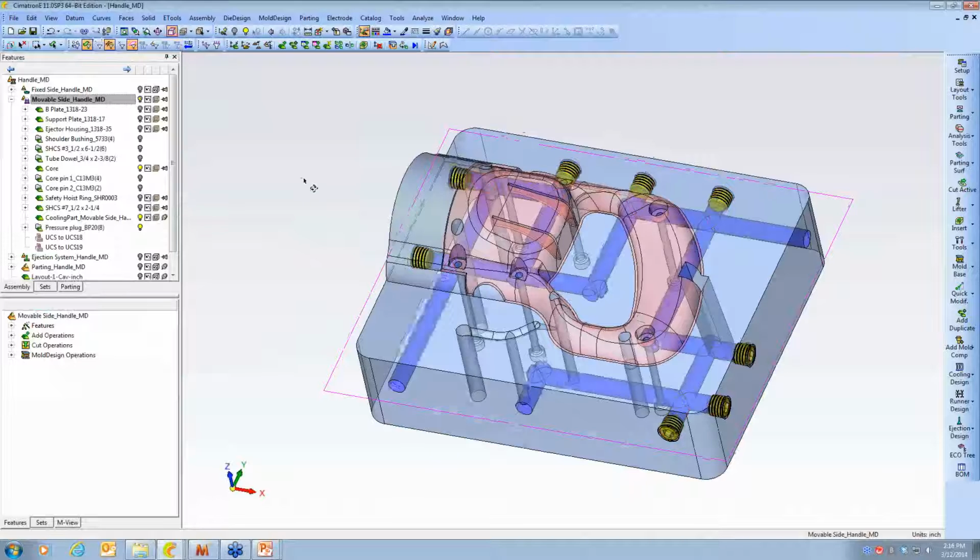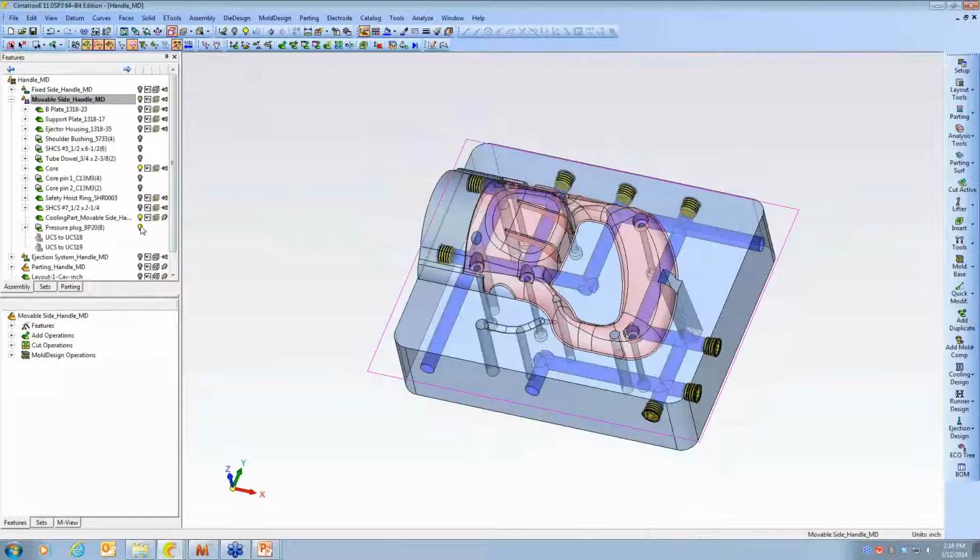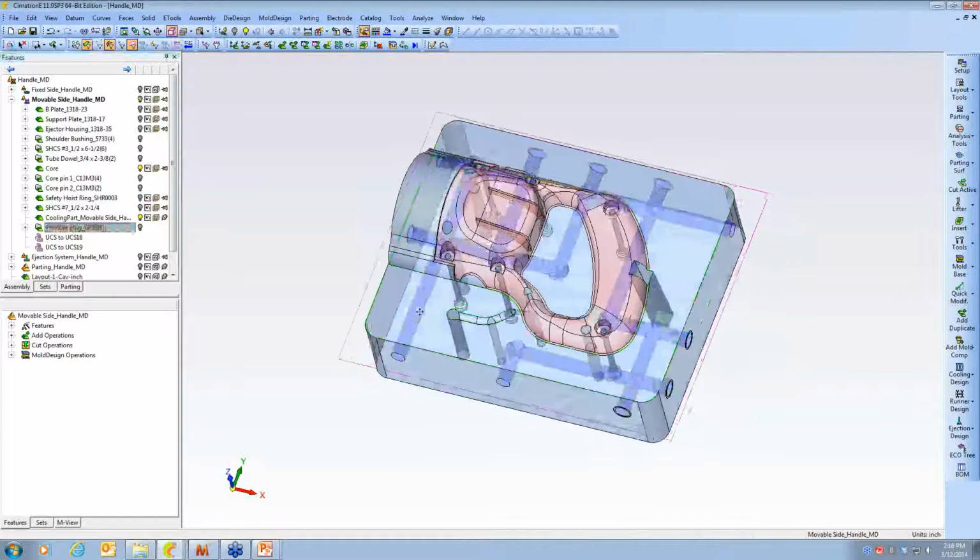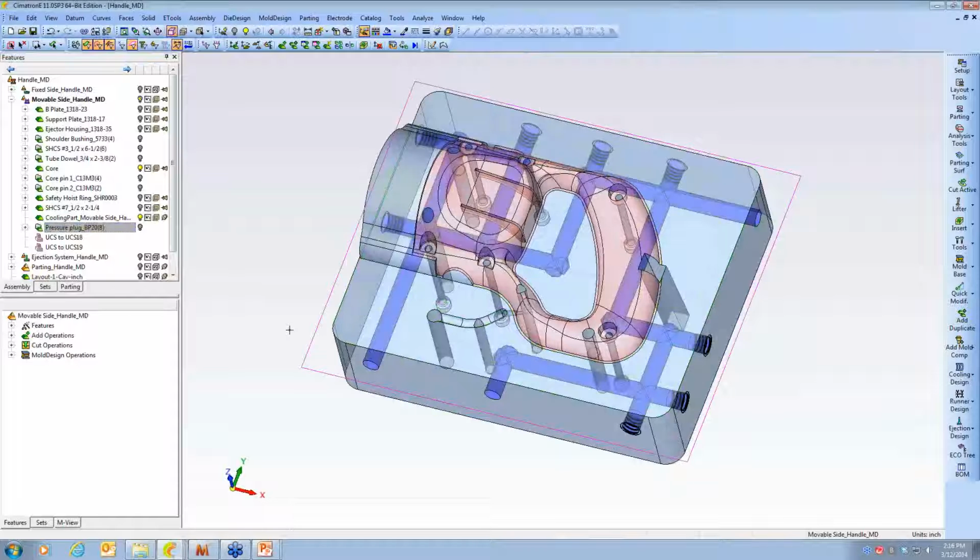Now those components are added to the design tree, and a bill of materials is being kept for this job. Another great time saver here is that when a catalog component gets added, it's also cutting in any pocket or thread that the component requires. Built-in holes like this really cut down on the repetitive tasks you have to do while designing.